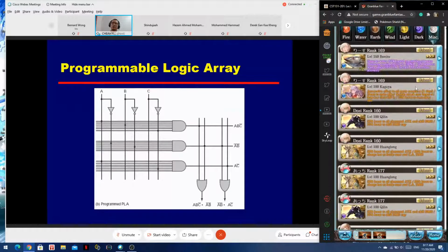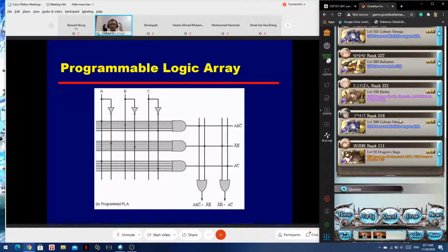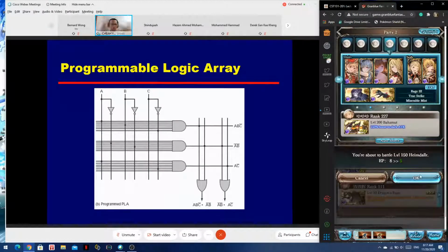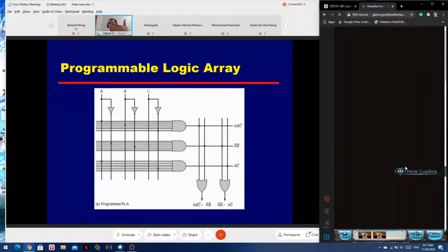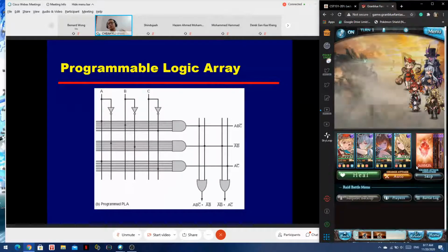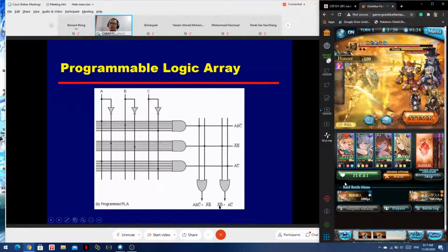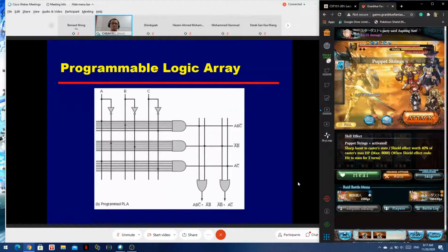All right. So I hope if you forget everything about PLA, you remember this diagram. So you have all these gates available. You have one AND plane and one OR plane. Then you fuse them together. Then you get the output. So in this particular PLA, you get two functions. Okay, you get two functions out of this simple diagram here, right?